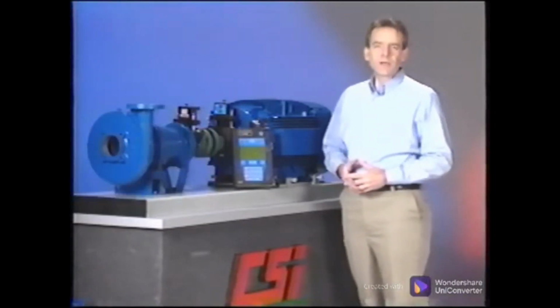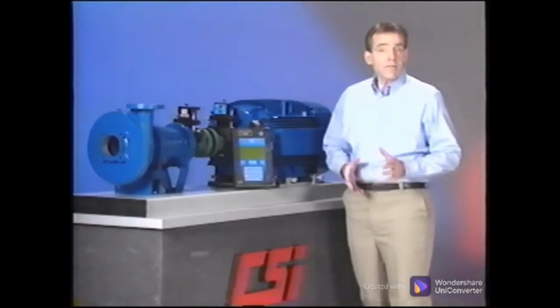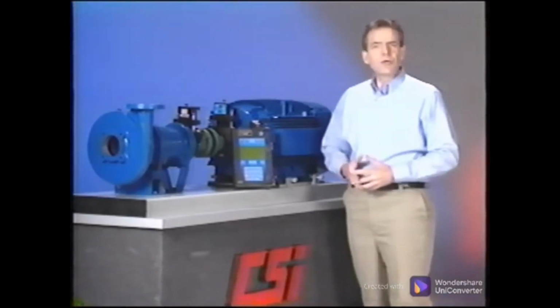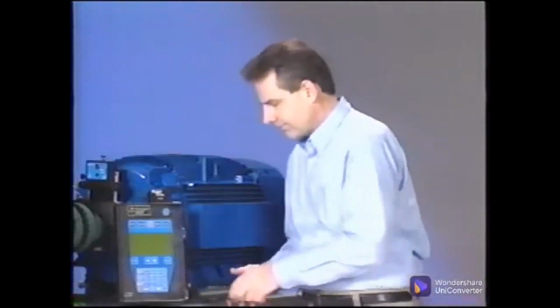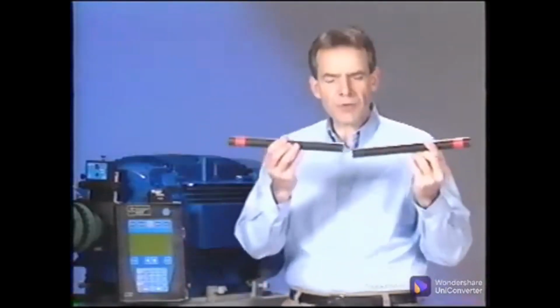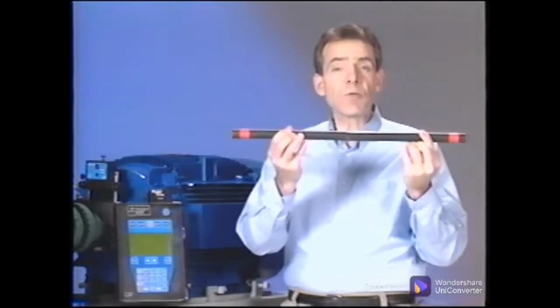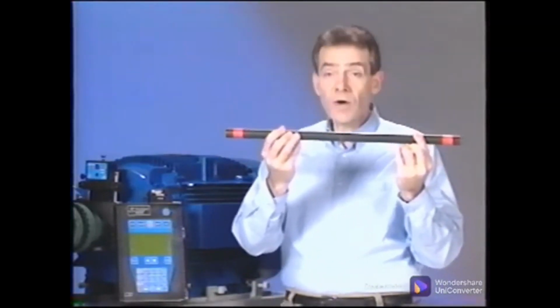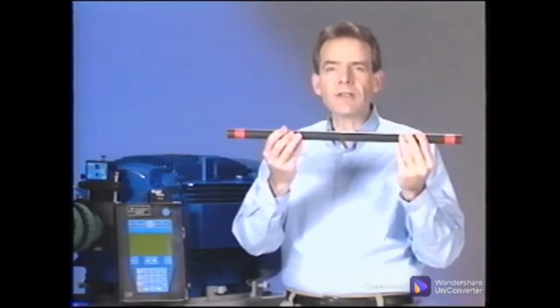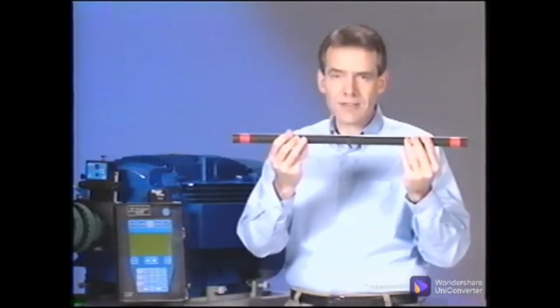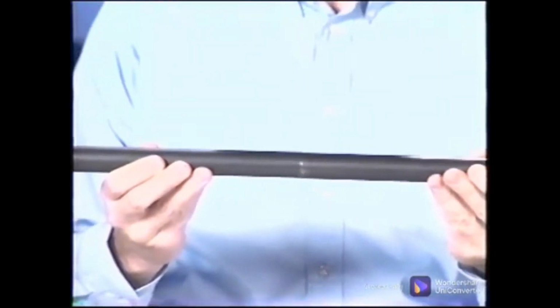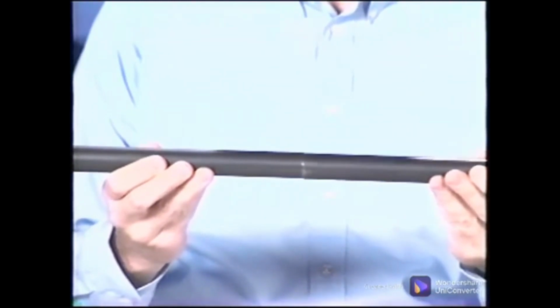Let's look at the characteristics of misalignment to see the effects on a machine and how they will show up in spectral and waveform data. When two shafts are aligned, their center lines will be a straight line from the end of one shaft through the end of the other. This common center line is called a common collinear axis. Misalignment, then, is any condition where the shaft center lines are not in a straight line during normal operating conditions.